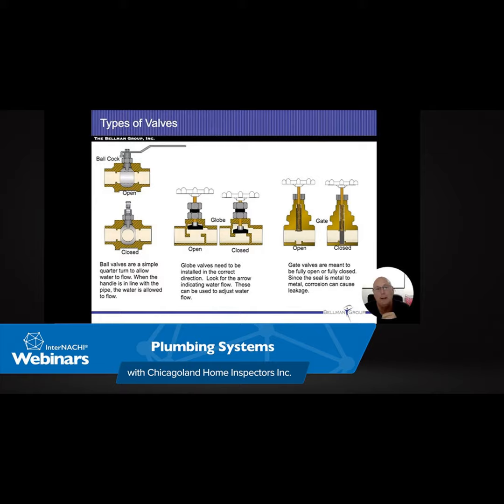Now, the city of Chicago is unique in the state of Illinois. Because they put their houses so close together, only 3 feet away from each other for those gangways, sometimes 5, they don't want all that water running on the surface. So they put their sump pumps into their raw sewage. They don't discharge them outside. It's not wrong if you discharge them outside, but they encourage you to put them into the raw sewage.